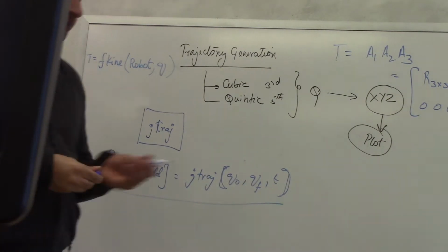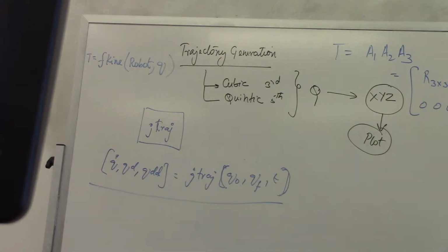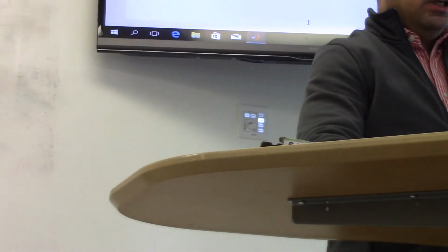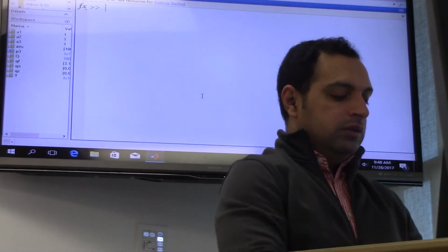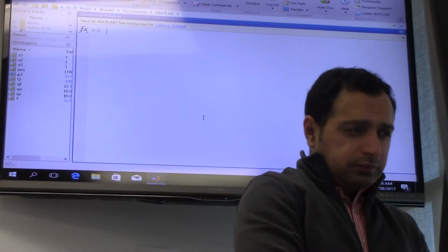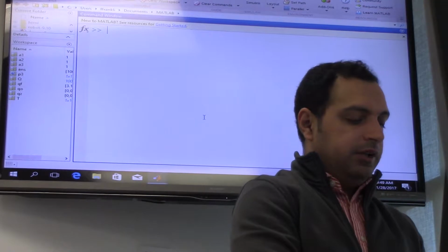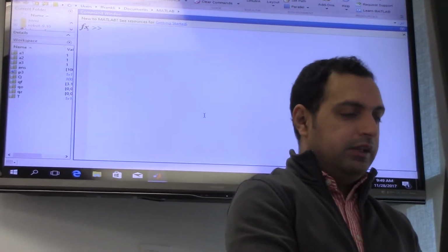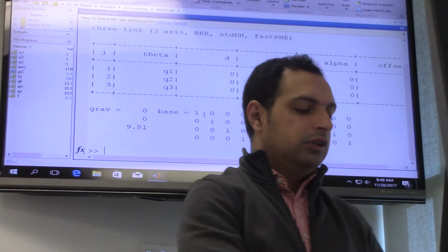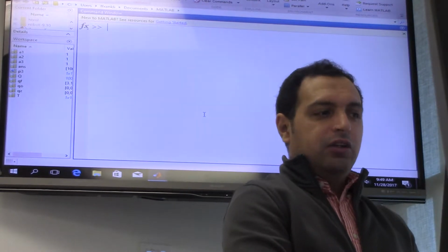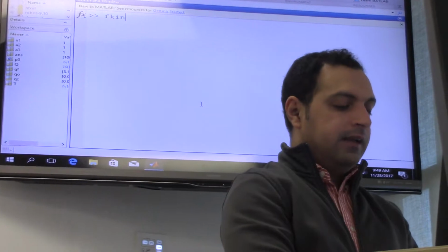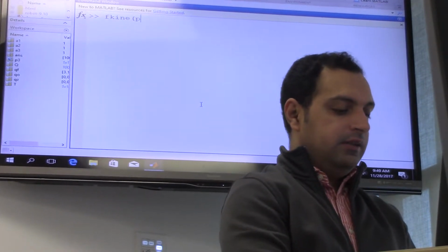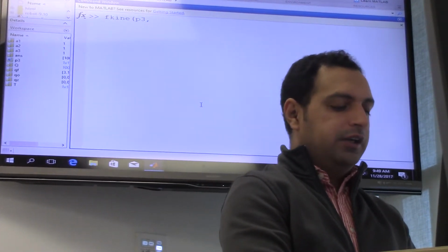So for example, let me go here and do a sample command. The name of the manipulator here is P3 because it's a 3 degree of freedom planar manipulator. So we'll use fkine over this. There are two ways to write this. First one, you can write it like this: P3, comma, Q, right? Q can be anything.